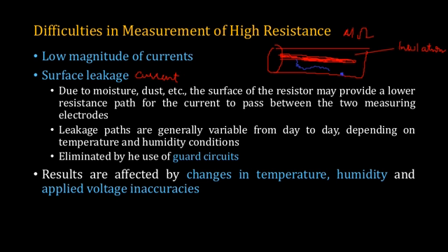These impurities can be in the form of dust particles that enter within the insulator during the manufacturing process, or some air bubbles which affect the total insulation properties. So such leakage currents can affect the overall performance.